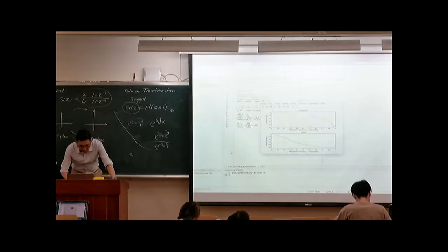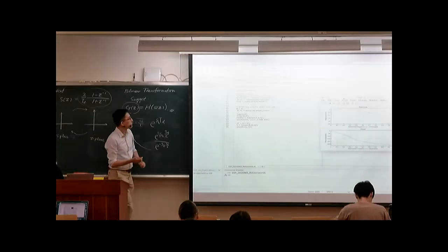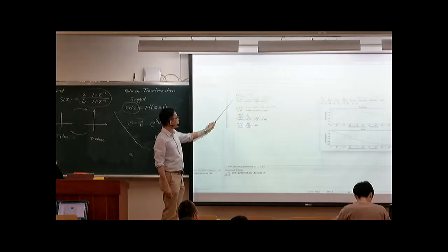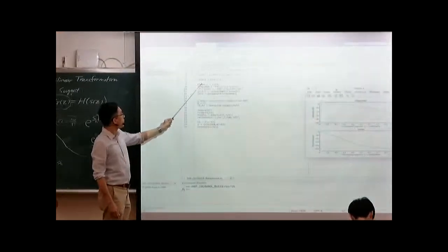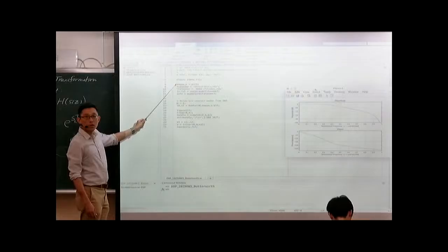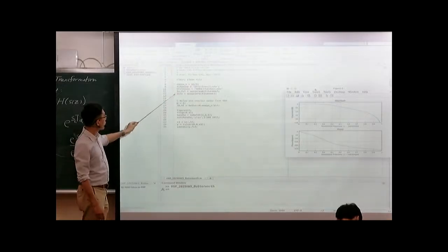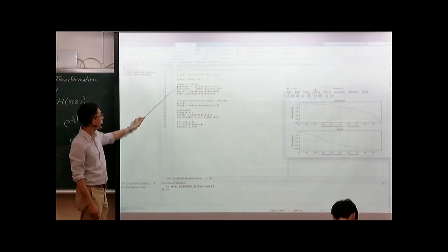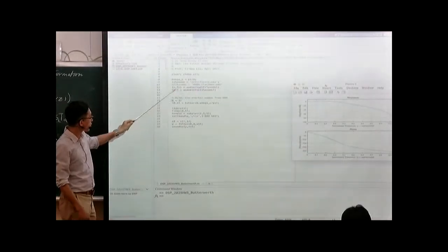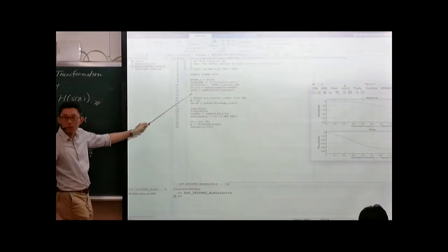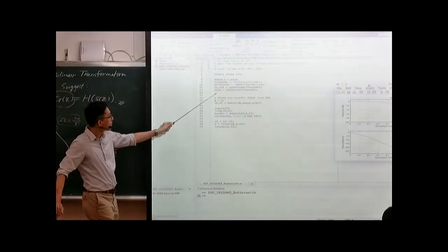All right, so as you can see in this code, in MATLAB it's very convenient, we can set the corner frequency in your design in G of Z. Set the corner frequency at pi/3, and then this part of the code, we read the audio file using audioread, and you can also check the audio info, sampling rate and stuff like that. And then one line.